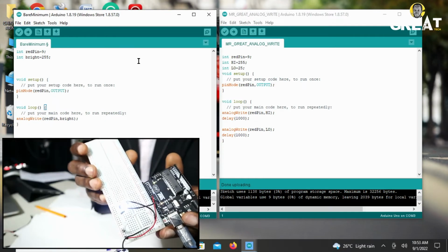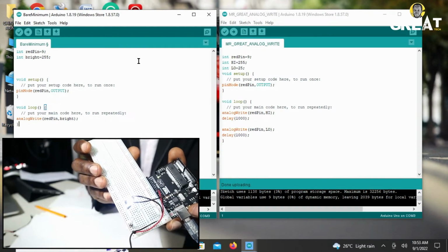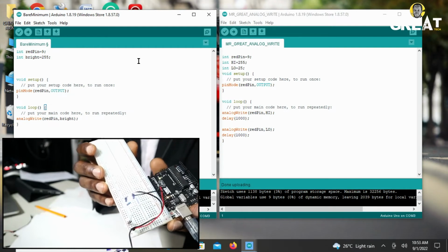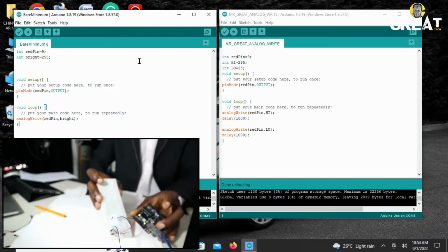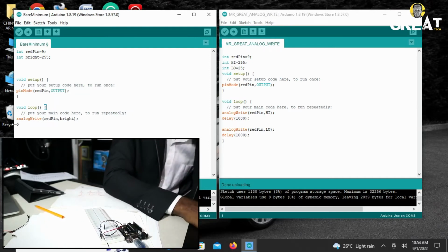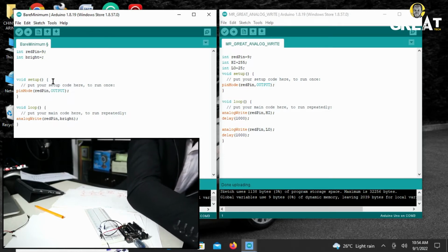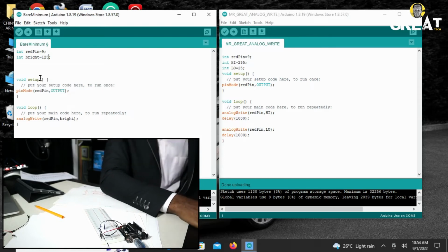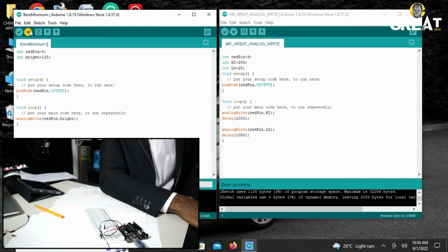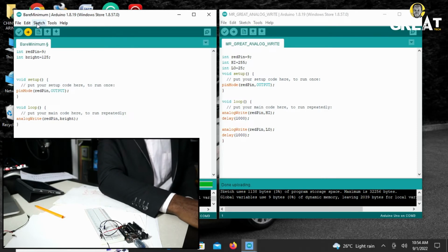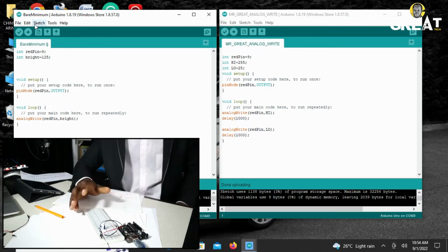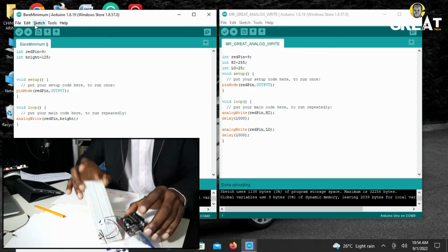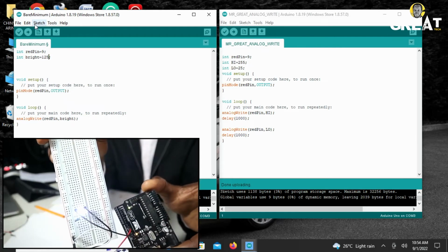It's just like digitalWrite. But now we are going to reduce the voltage. This is just 5 volts out, so now we are going to bring the voltage down to half of it. Maybe let's put 125, which is 2.5 volts. So easily you come to this place, put 125, then upload it and see. You see the buzzer will change sound. The buzzer has changed and it's not getting up to 5 volts again, and the brightness of the LED has reduced.